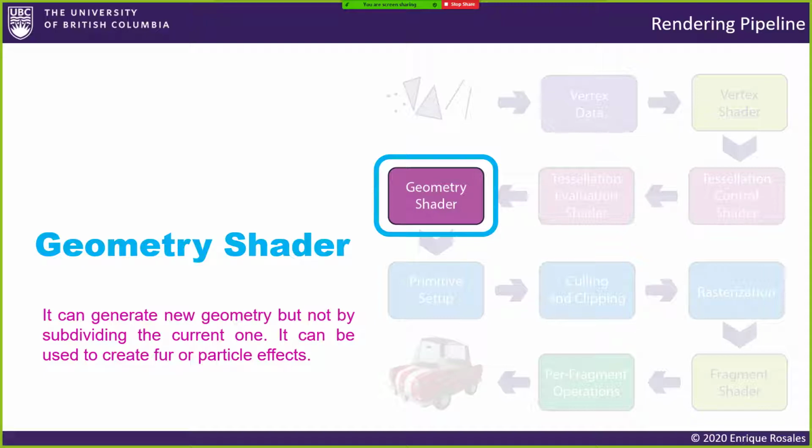Could you attempt to derive the connectivity information through the normals alone? That is, if the dot product between neighboring vertices is positive, you can assume they are connected? No, that is not possible. You cannot get connectivity information from the normals. The normal is just a vector, and it doesn't tell you anything else but the direction that is orthogonal to that vertex. There's no way to get the connectivity.